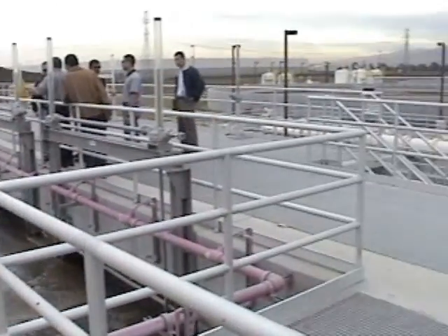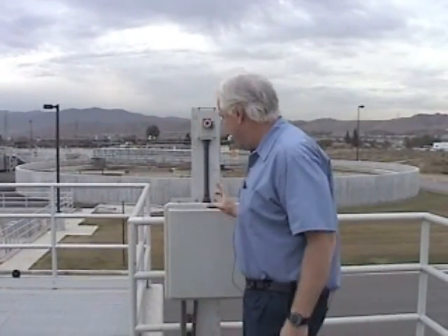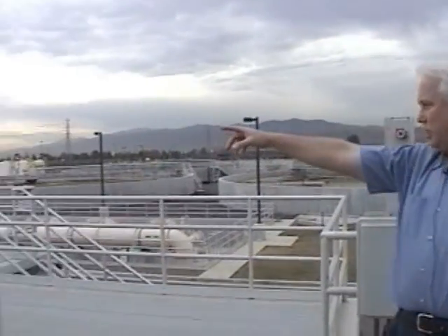Under normal circumstances, they'll always be on. In a power failure, like if we switch over to generator, they will fail, and it's real important to start them back up. I think one of the things about the MLR pumps that's important is in a power failure, there's so many things going on that these can be overlooked because they're not readily visible. So I think it's important to remember in a power failure, remember to check the MLR pumps. And there's displays that will show you the status of this. There's one for aeration basin 4 where I'm standing, and then there's another one, same spot on train 3.